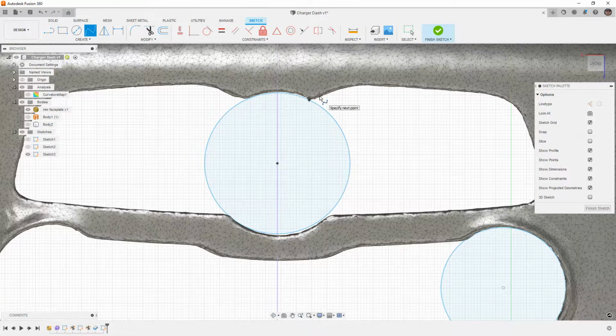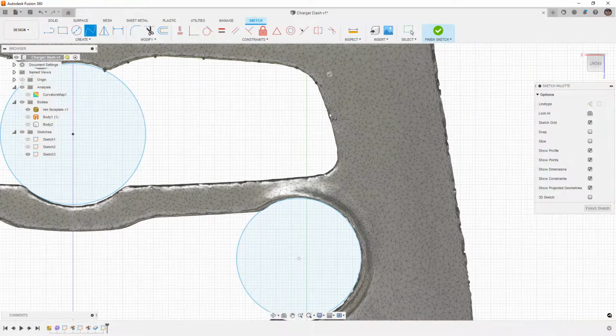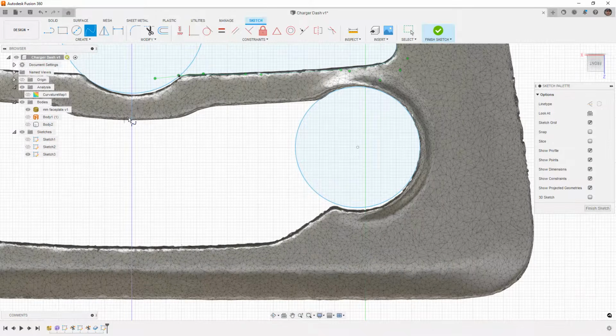And it kind of depends. In reality, this is probably an arc. This is a very gradual arc. These are probably not splines that they use to create these, but we're just going to work our way around adding some points. Again, you can add straight lines if you want. I'm just going to try to get it close. Say OK, and we'll do the same thing over here.